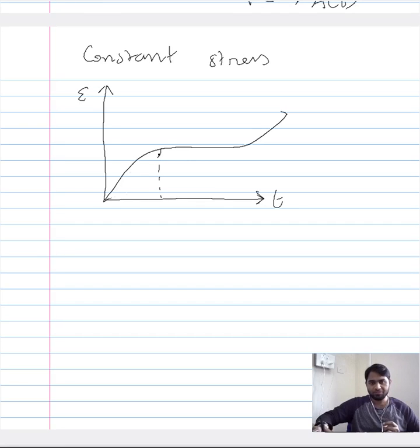the slope of this curve is gradually decreasing and changes to a rather constant region. So in the first region, the slope of this curve is gradually decreasing. There is some sort of a constant slope, but it is gradually decreasing. So this we could demarcate as 1. This is one of the regions of the curve that we have plotted. We could refer to this as the creep curve, because that is what we are studying essentially.